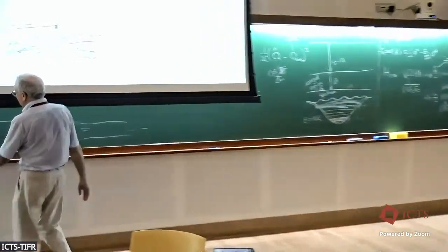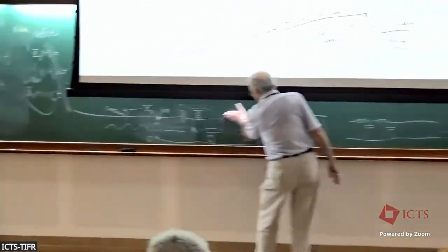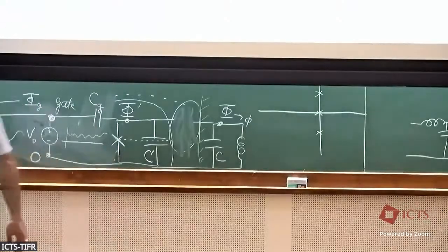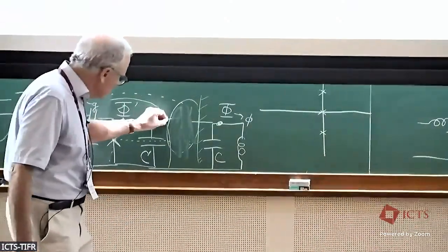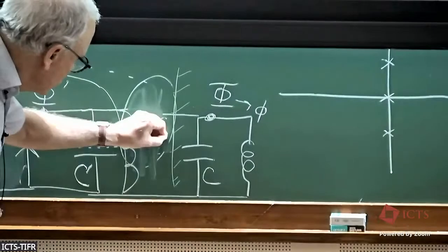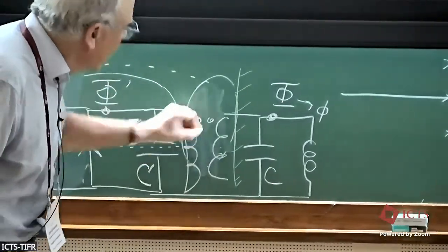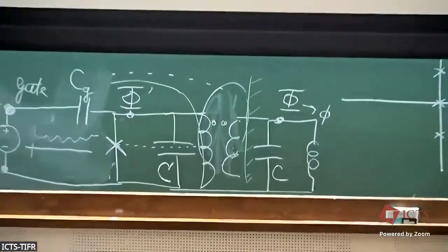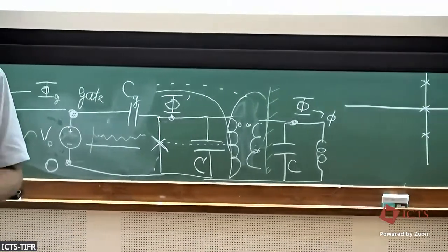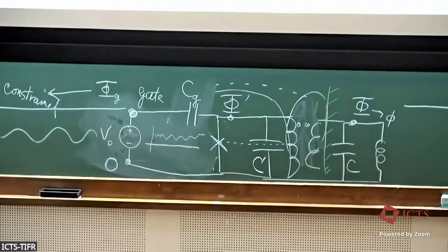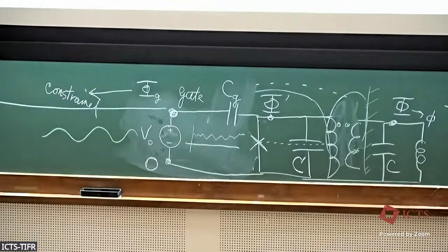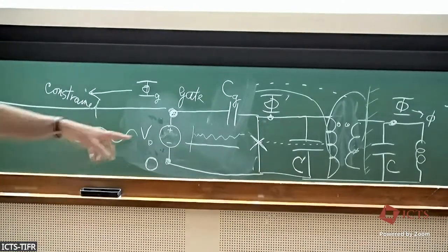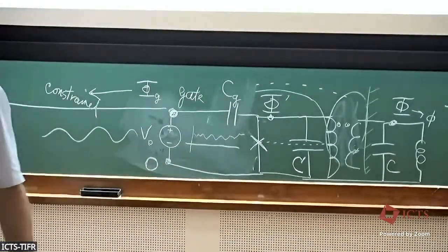And actually, you can read a section of our book where we indeed study this circuit, which has sometimes been used. So you have this, and you have this, and then you have what I haven't introduced, which is mutual inductance coupling, but that's also straightforward from this energy formalism to include. I think the reason it's not done is it's just more straightforward to make capacitors on chips than inductors, and especially to get mutual inductance is very awkward on chips.